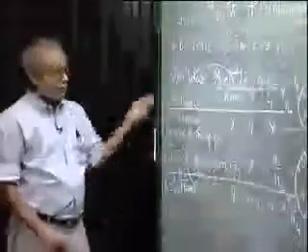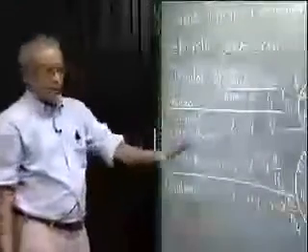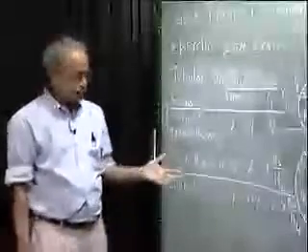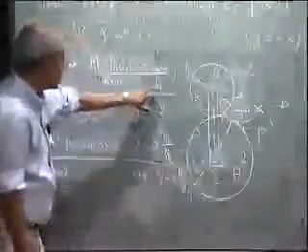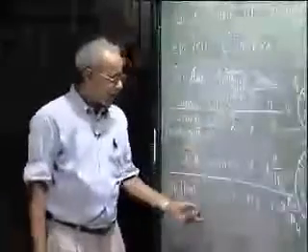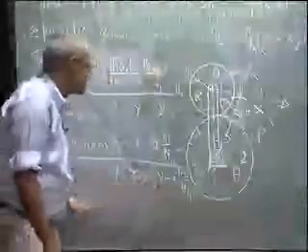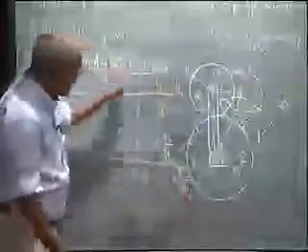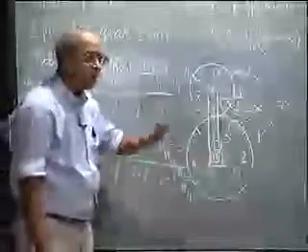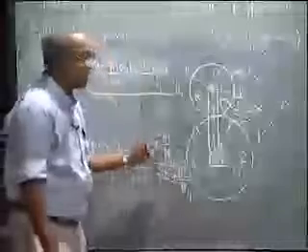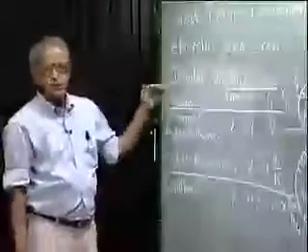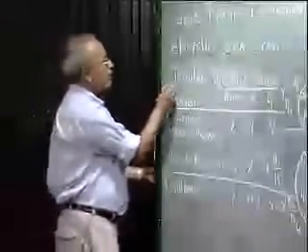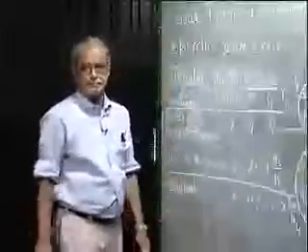Now as I said, it is a 2-degree of freedom mechanism. All the output speeds can be determined only if you give me 2 definite inputs. That means 2 of these speeds must be known, then only I can determine the third. So I get 2 equations by equating the given speeds, and I can determine x and y, and once I know x and y, I know the speeds of all the elements because they are all expressed in terms of x and y. Of course the numbers of teeth are given. This is the method that we shall follow, and I shall solve a few examples to show how to use this tabular method for analyzing the epicyclic gear chain.